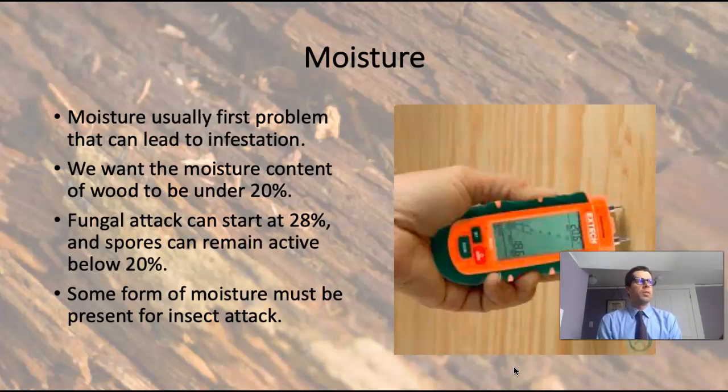What can happen, especially with mold in homes, is we get all of this wet lumber and we put it into our house and we build it so fast, we get it insulated and sheetrocked so quickly, that we trap all of that moisture in there. Mold can start growing, decay can start to happen. Under the house is where a lot of decay happens, primarily because we can't see it. We can't see what's going on down there. We don't crawl around under the house very often. Maybe there's inadequate ventilation, but we'll talk about that pretty soon.